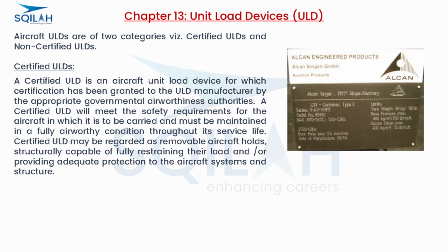Certified ULDs and non-certified ULDs. Certified ULDs. A certified ULD is an aircraft unit load device for which certification has been granted to the ULD manufacturer by the appropriate governmental airworthiness authorities. A certified ULD will meet the safety requirements for the aircraft in which it is to be carried and must be maintained in a fully airworthy condition throughout its service life.